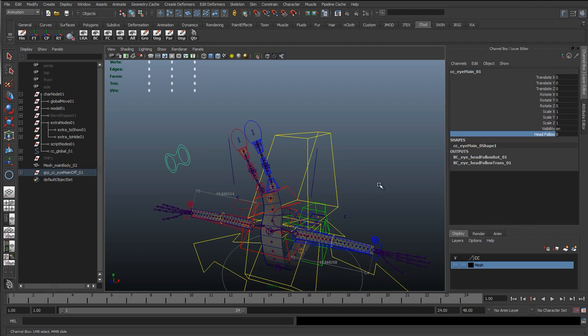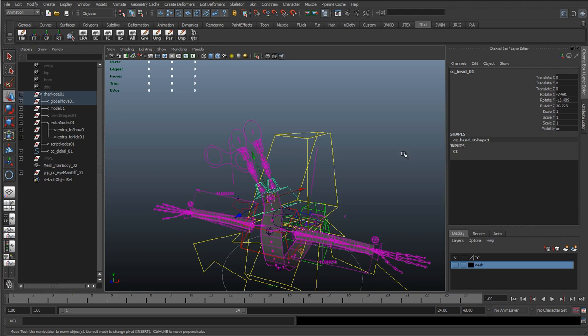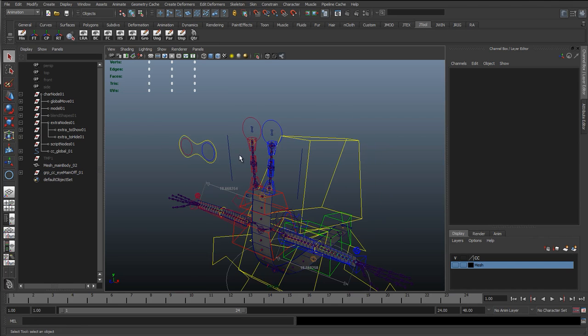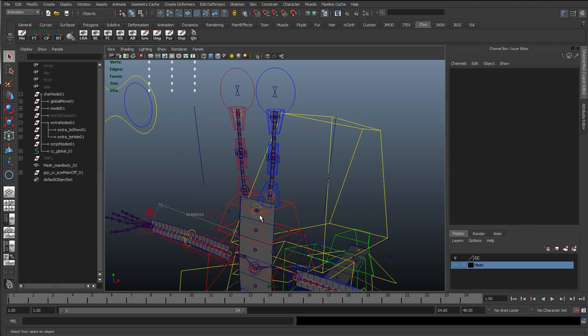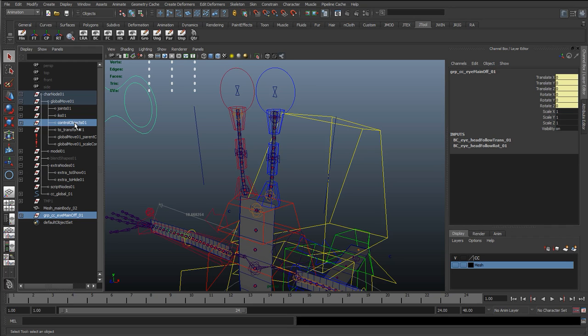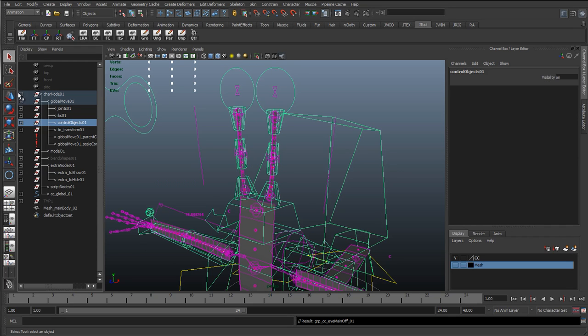blend between to 0. And this is again why I like this control, because if we blend in here, the eyes are going to be aiming here and then darting across. So I quite like that for the head control. Okay, so resetting these all back to 0. Put the follow to 1 because that's its default. We didn't create the tie control, it was one from previous, so we don't need to parent it. One thing we do need to parent is this group we've made with the eyes controls in it. So go to the global move, control objects, and just hit P to get that in there.